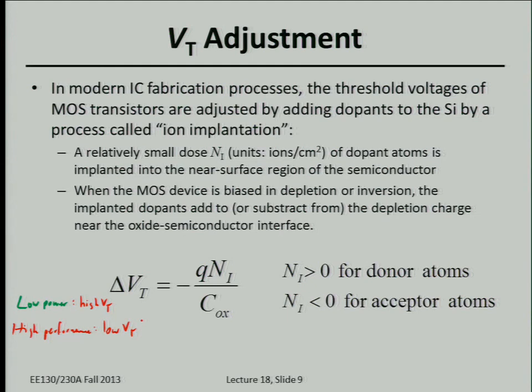Usually on a microprocessor chip or some system-on-chip integrated circuit, some parts of the circuit you want to operate at very high speeds, so high frequency. And other parts you just care about having low power consumption. In a memory like SRAM, if you just want to store information, ones and zeros, you don't care about making very fast calculations, so usually you want those transistors to have high threshold voltage, so they have low off-state leakage current.